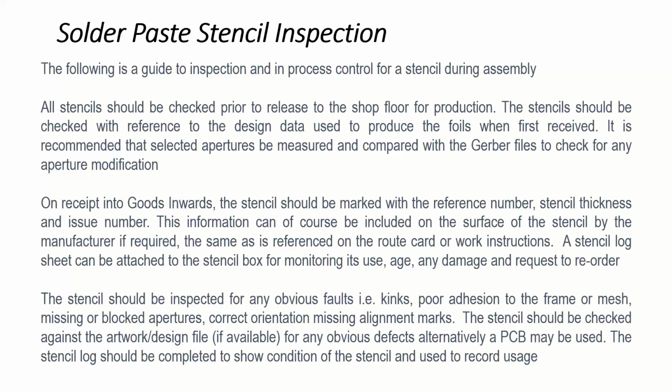I normally look at the four corners of the stencil and then the finest pitch on that stencil. I'm not saying I don't look everywhere, but that's what I would normally do. Four corners and the finest pitch. And that gives me confidence whether my process, whatever technique is being used, has achieved a clean stencil. And then I return it to the rack for reuse.